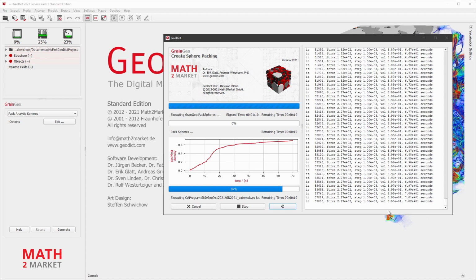With now just below 80% achieved packing density, the solver now needs most of the time to achieve the last few percentage points by small displacements of the spheres. If there is no improvement of the packing density over several iterations without the spheres penetrating each other, the solver aborts and notes the reason for the abort in the result GDR.